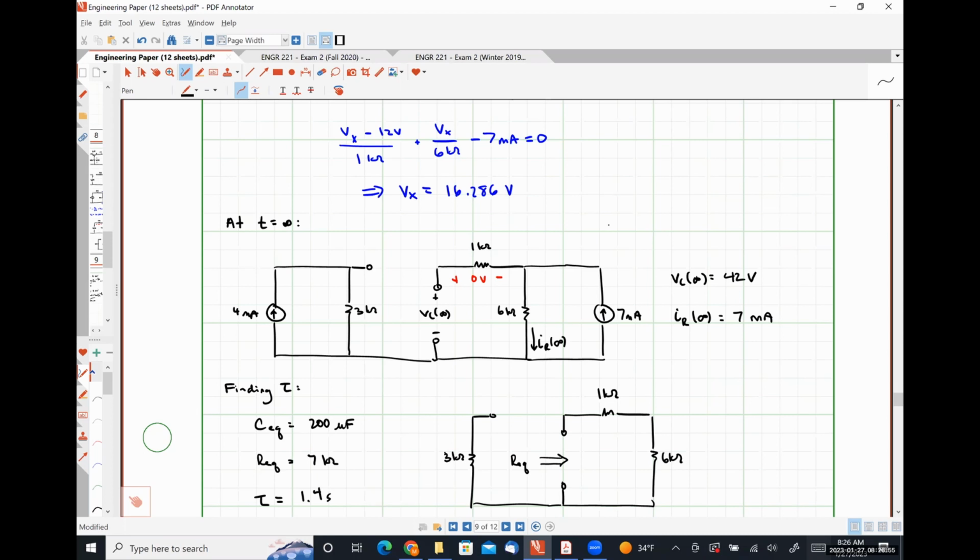That is exactly what voltage is. Voltage is by definition the difference in electric potential between 2 points in a circuit. That is from the second day of class. Yes, absolutely. So you're just measuring the voltage drop over the capacitor at infinity. Because I was out, we didn't get to do the lab where we literally do this, but we would be using an oscilloscope to measure the voltage as a function of time for a capacitor, and we would see that it effectively exactly matches the mathematical model that we've developed. An exponential decay or 1 minus an exponential rise as it charges.